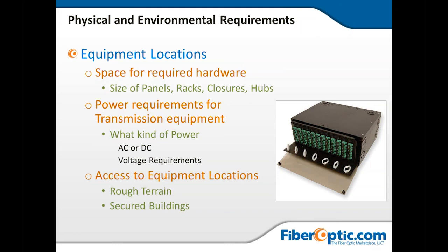DC gives us the advantage of having battery banks for backup that will give us several hours to days of backup power. And a lot of equipment will run just as happily on DC. And for those few things that you do need AC, we can always run inverters to take it to an AC level.